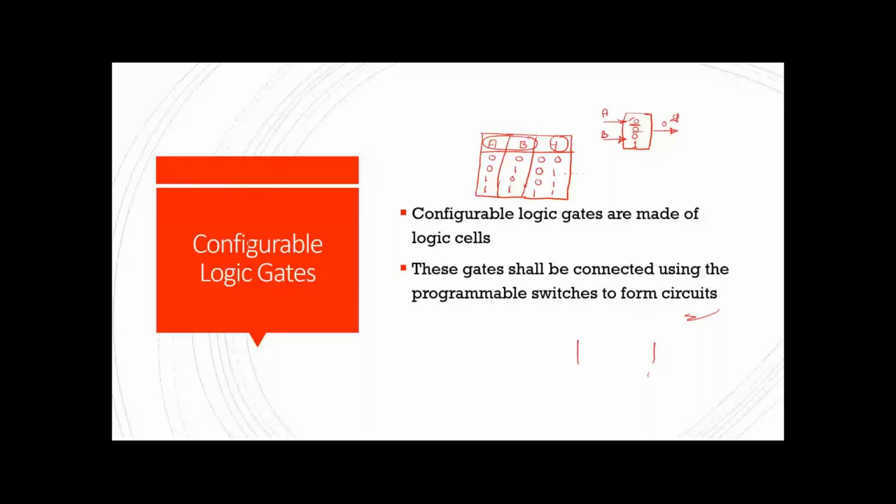So this is something like one logic cell, the basic configurable building block of an FPGA, which is called a lookup table. This is how we design the circuitry in the FPGA. Basically, we are modifying the contents of these logic cells. If it is 0, 0, 0, 1, this particular logic cell will act like an AND gate.